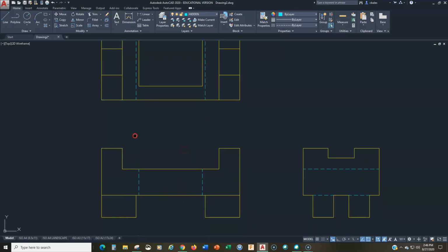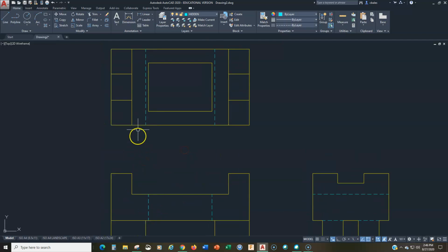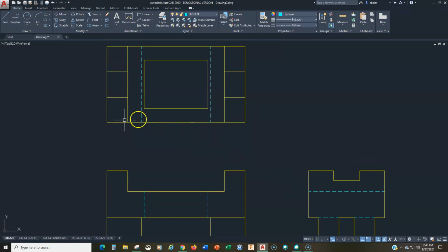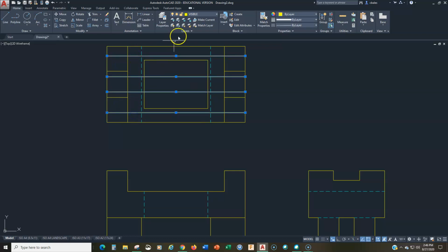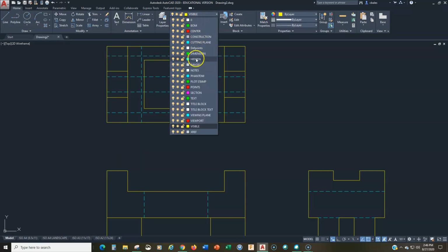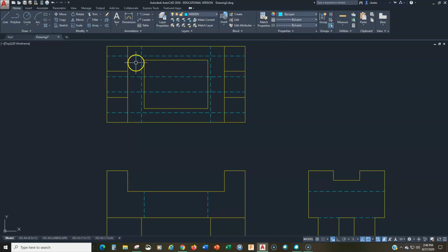Now the rectangle here, this actually doesn't go all the way across. This is going to be a challenge. So offset 7, I'm going to offset 7 here and here, and offset 15. Now, while these are long and I can easily identify them, I'm going to create hidden lines right there.